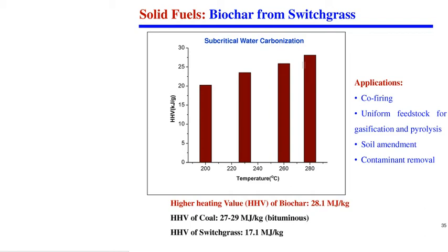So what is our approach? This is one of the studies I am presenting from my lab group, done in the last 2 years. We developed a process which we call flash pyrolysis under subcritical water condition in a continuous flow reactor. Algae can be fractionated into 2 phases. One is a lipid-rich phase, and the liquid phase is mostly protein rich. So now we remove most of the nitrogen as amino acids or peptides. The lipid-rich phase can go for biofuel production by catalytic degradation, and the protein phase can be used for bioproducts or nutrient recycling.